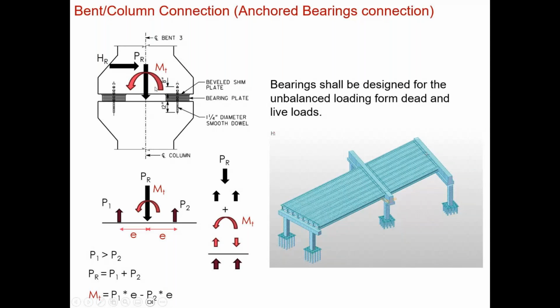In a simplified way, the vertical loads put compression on the two bearings. The torsional moment is resolved into a couple of equal forces based on the lever arm from center to center of bearing. Those forces are compression on one side, tension on the other side.